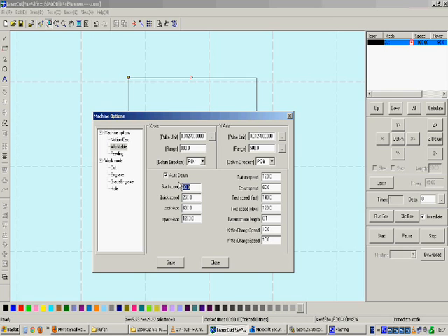So you can use the start speed as 10 and constant speed as 10 or 20 for those, because the cutting speeds are around 10 or 15 millimeters per second. But if you want to make faster cuts, for example in the textile industry, while cutting fabrics, you may require even 150 millimeters per second.